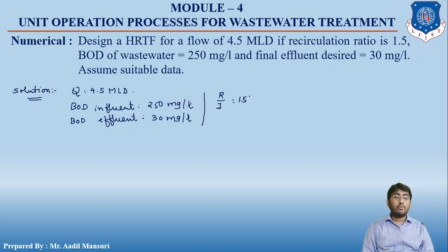Now the first step involved is to find out BOD of wastewater in kg per day. In 1 liter, 250 milligram of BOD is present. So how much BOD will be present in 4.5 MLD of wastewater? I am writing over here: BOD present in wastewater.